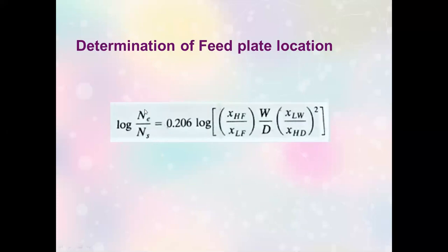But nonetheless, in here, you could see that using only the x of the high boiling point component of the feed and the x of the low boiling point component of the feed, together with the amount of the bottoms liquid and the distillate, and again the x of the low boiling component in the bottoms liquid and the x of the high boiling point component of the distillate, you'll be able to get the ratio of these two.